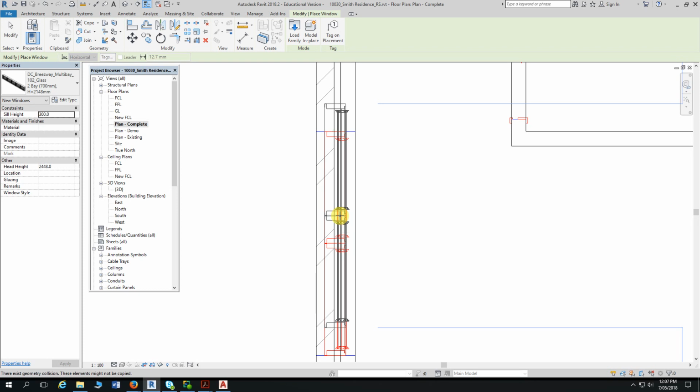As I said in my instructions, make sure they're not inside out. The important thing is to put them in so the louvers are pointing downwards on the outside. So just place the window close to where it needs to go, so about there.